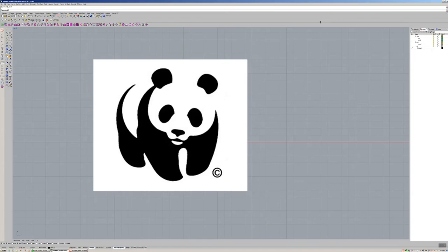Right now I have something I call my work layer, which I'm clicking on, and it's a greenish, bluish color. So now when I draw the curves, I'm gonna see it. Otherwise it would be black, since the default is black, and we wouldn't be able to see it. So I chose a color that stands out, this kind of aqua color.